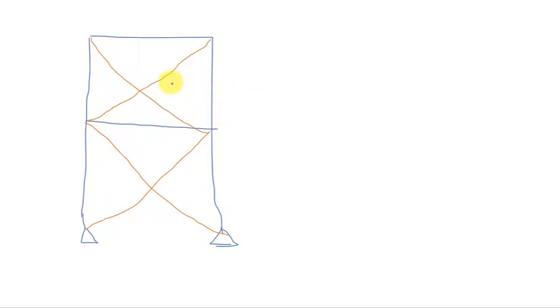We have both vertical bracings and horizontal bracings, but today I want to just speak of vertical bracings. I will do another video so that we can explain how exactly the horizontal bracings work. They're called horizontal bracings or plan bracings, right? So this one is for steel structures.